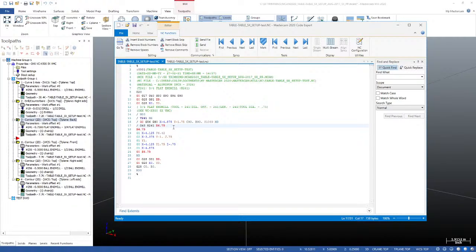So if you had a machine, for example, where you wanted to do multiple toolpaths in a row, but you wanted the ability to restart any one of those particular toolpaths, because maybe you needed to change cutter radius compensation or make an adjustment of some sort, speeds and feeds, and you wanted to restart at that position, you can tell it to force tool change, but you can use block delete before the tool change and then turn it off after, and it will just go from one operation to the next during normal cutting.